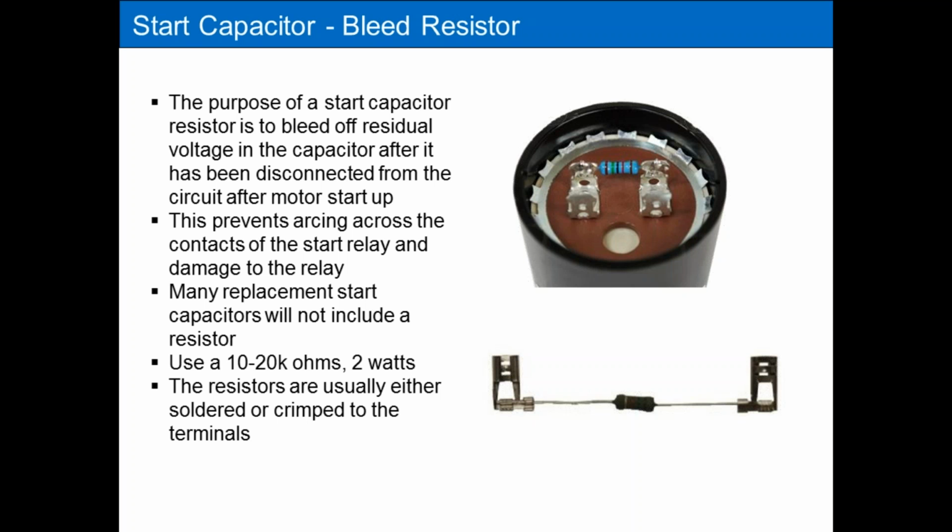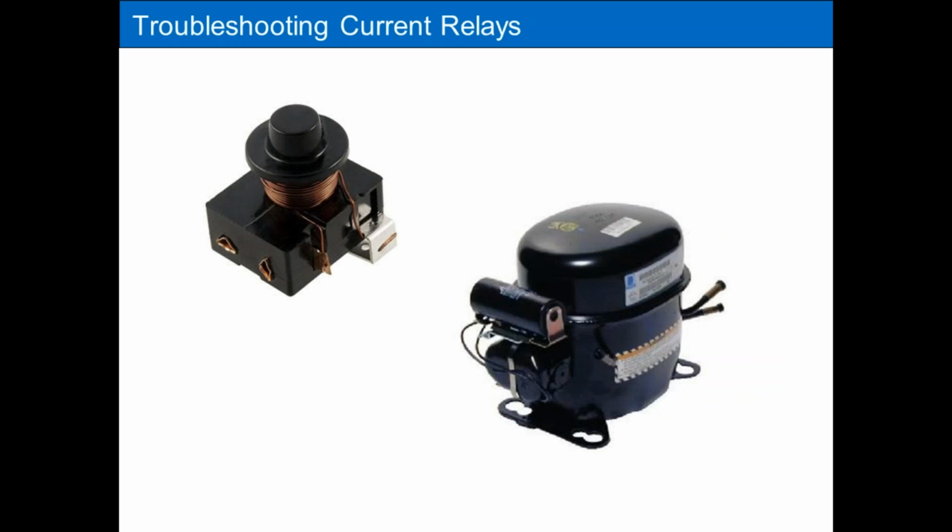So please make sure you put a bleed resistor on any replacement capacitor. If yours doesn't have it, you can buy resistors from your wholesaler that you can attach to your replacement capacitor. All right, let's talk about a relay.